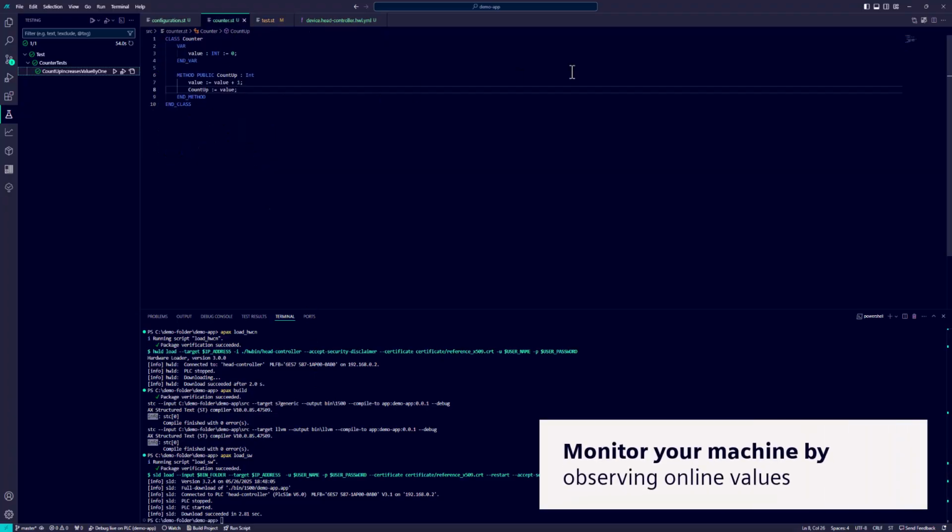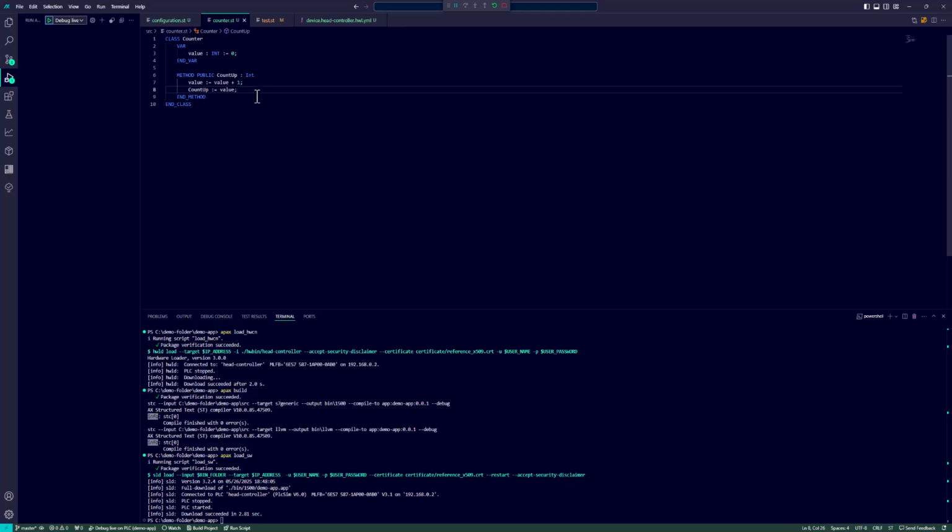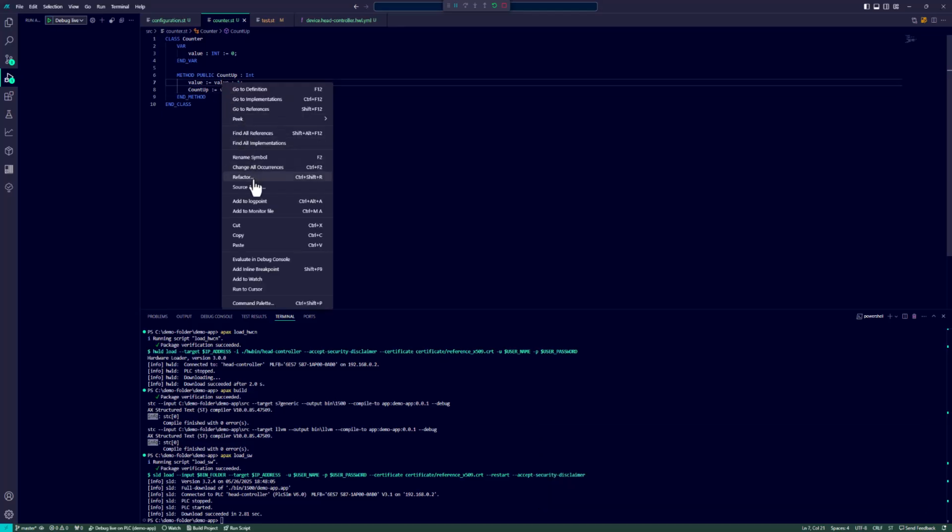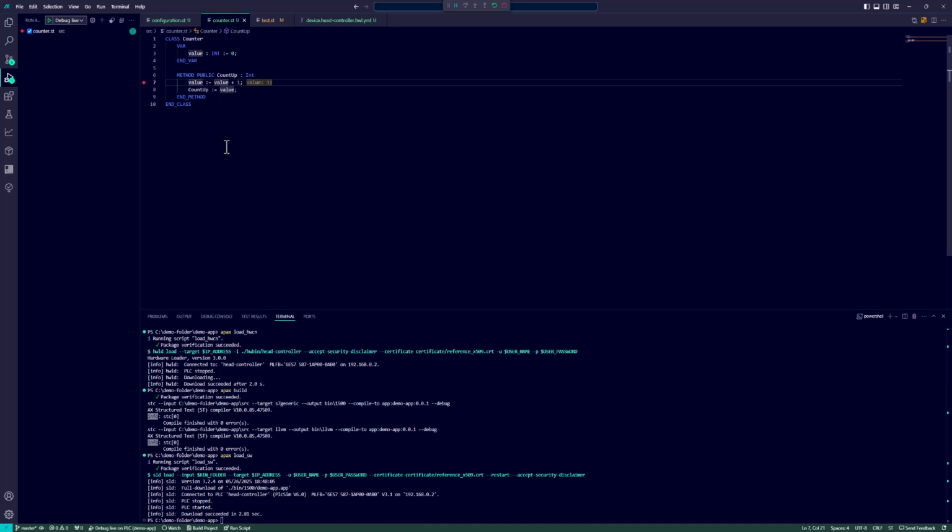Verifying the correctness of your implementation is supported by accessing the PLC online and extracting values during runtime. Navigate to your implementation and go online. This allows you to create log points inside the source code which will show the development of online values of the selected variable.